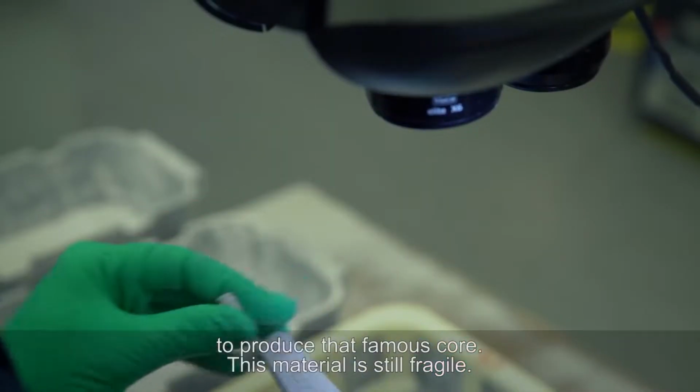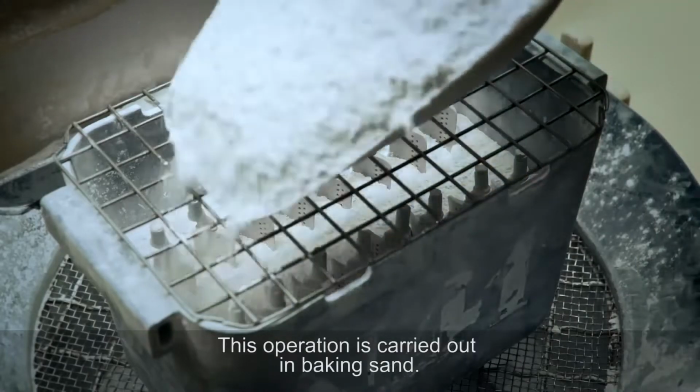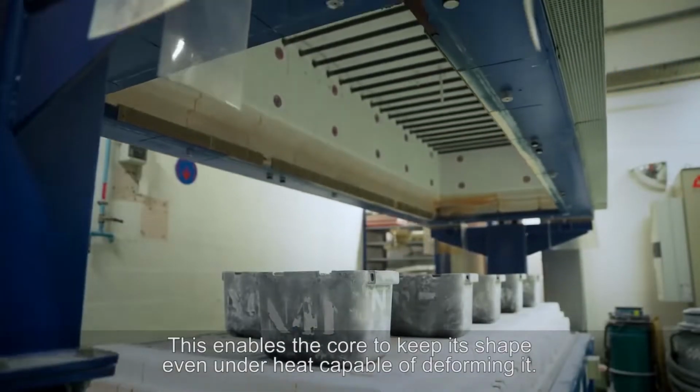This material is still fragile. We therefore need to cook the core in order to harden it. This operation is carried out in baking sand. This enables the core to keep its shape even under heat capable of deforming it.